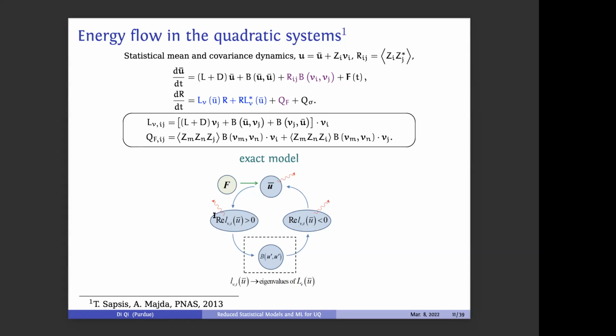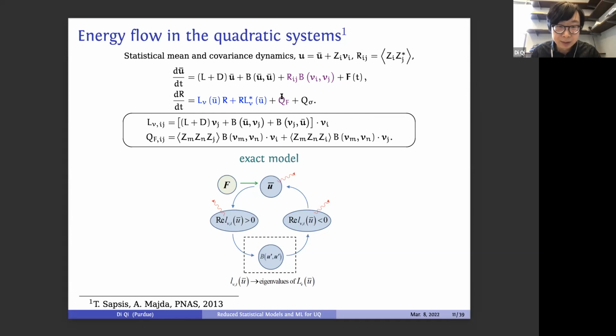And this is just for the starting time. When the energy level develops in time, the third order moments take over. So here is the crucial role of the third order moment. It extracts the additional energy in the unstable subspace and injects it back into the stable one to get dissipated, and then finishes the energy cycle. This is another way to show the central role of the nonlinear term, and that's why we cannot simply ignore it.